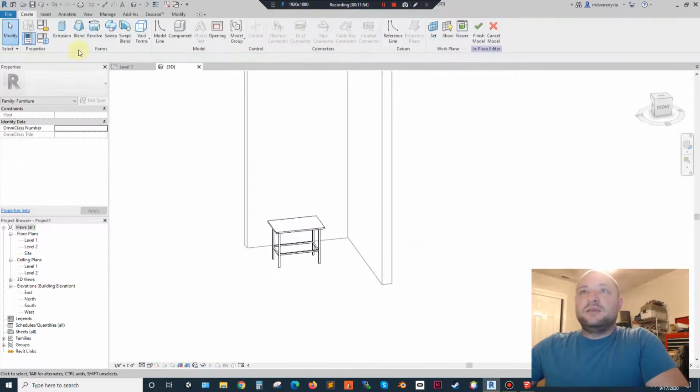Now there are other options here, as far as you can do blend, you can do revolve, you can do sweep. So think back to a lot of the things I showed you guys for the SketchUp portion of the last class, where we covered modeling in there. There are a lot of things like the sweeps where you can then go in and model different faces, or you can modify or merge extrusions together to create cabinet faces.